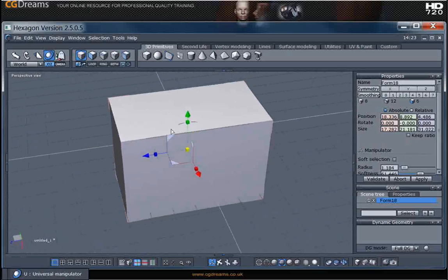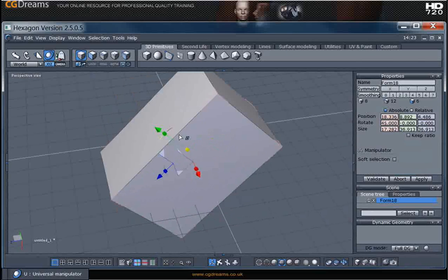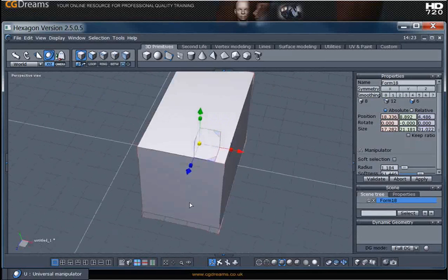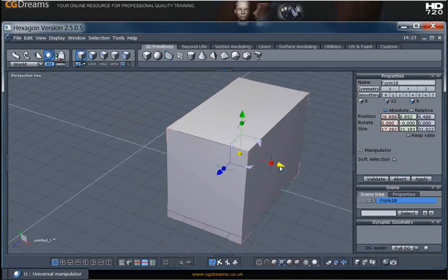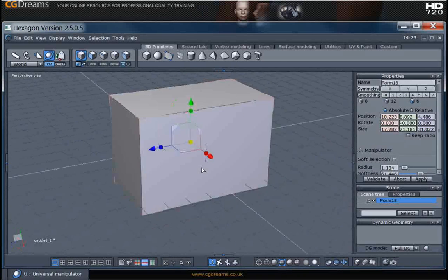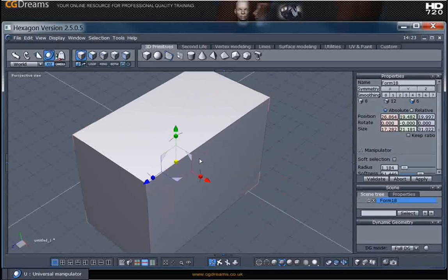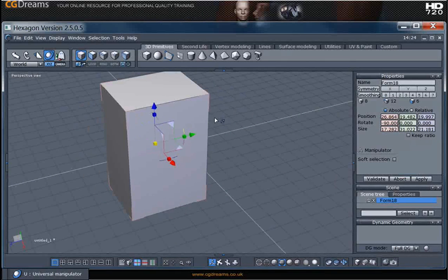In addition to this, you can see these little tiny handles that we can click on and rotate as well. And just to mention that all of these manipulations can be used in conjunction with the Shift key to help us lock to a specific axis other than the translation, because you'll get this funny movement going on here because it's got nothing to lock to. So if we wanted to rotate, say, 90 degrees, we can hold the Shift key and it will help us lock to that 90 degrees.